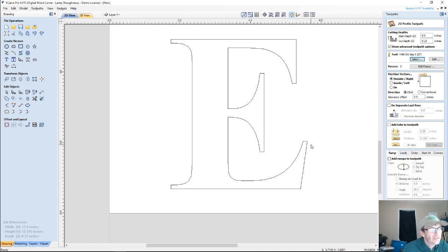Do I want to be on the outside of the line? Let me think here real quick. Where do I want to be? On a nice V cut right on that line. I'm going to cut on the line in this case. Or I could be on the outside of the line and do an allowance offset, which means it's just going to bring the bit in that diameter. But I'll split the bit. I'll be on the line for this.